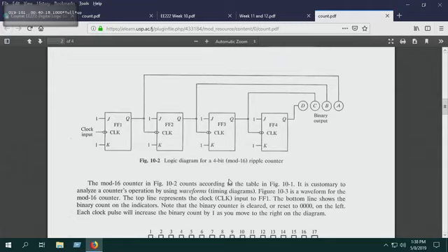Now, this is 1, this is 1. Remember the theory of JK. What does JK do if both are 1? In SR, if both are 1, what happens? There's no flip-flopping; it's invalid, a no-go zone. Not used, strictly not allowed. That's why we move away from SR in asynchronous counters.